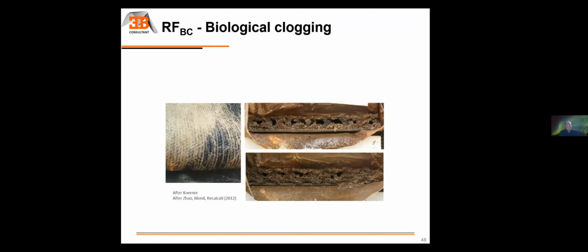Biological clogging. When you're draining organic leachate, like a leachate from a municipal solid waste landfill, you can have biomass developing, you can have some biological activity developing, you can have some roots developing into the product, and this needs to be addressed.